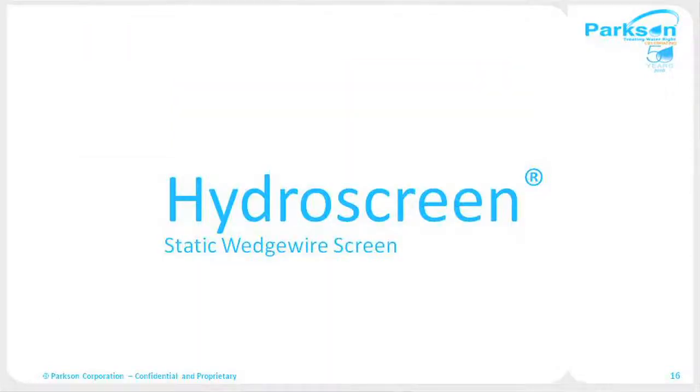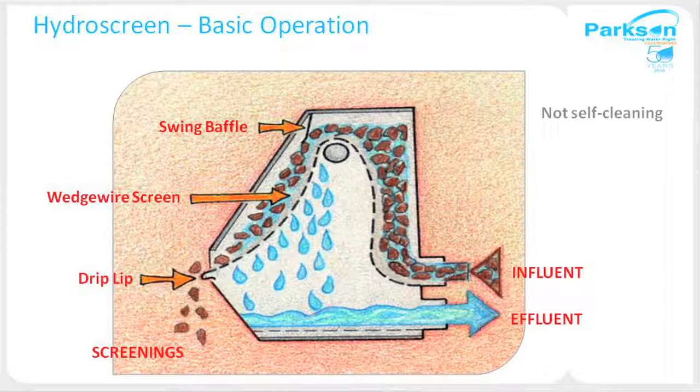So the first screen we're going to look at now is the static screen, Hydroscreen. Here we see a schematic of the Hydroscreen. Basically, the flow is pumped from the back end of the screen. As you can see, the influent comes in. The water fills up the influent head box, and then it moves on top of the weir and goes over to the screening media.